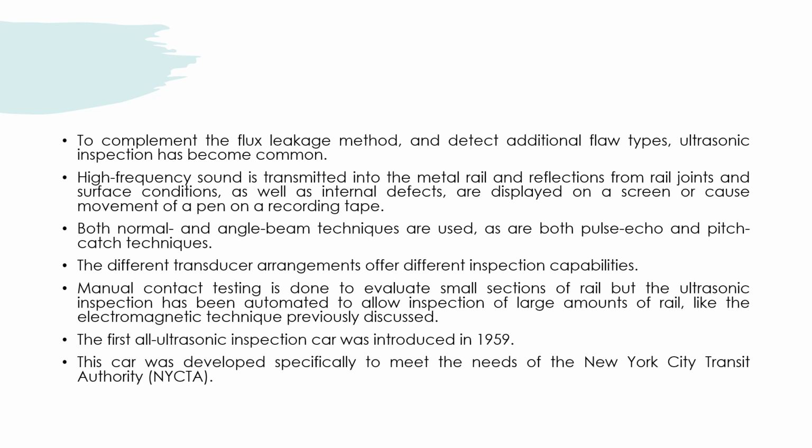Both normal and angle beam techniques are used here, as well as both pitch-catch and pulse-echo techniques. The different transducer arrangements offer different inspection capability.